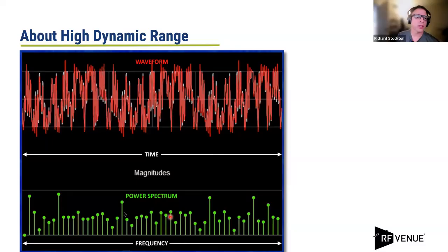Yeah, harmonics are created by non-linearity with one frequency, but we're focusing on people who are going to use more than one frequency anyway. So that's why you have to pay attention to the intermods as well. It's basically we're trying to avoid noise in all areas here, and the intermods are the most out of control. Will kill your system instantly.